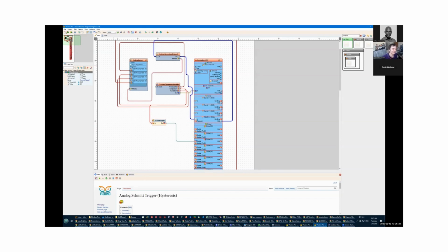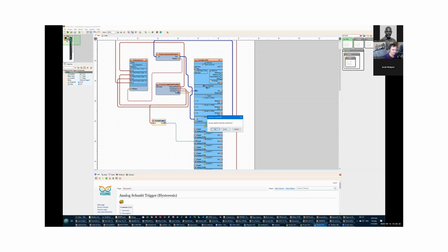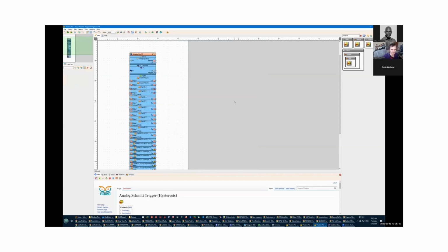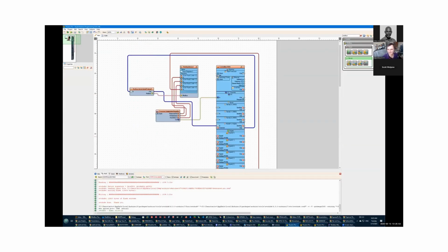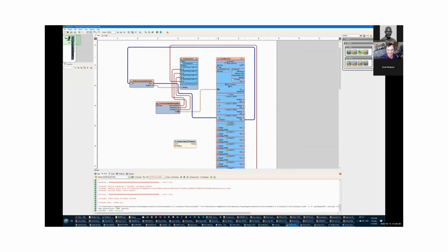But that being said, okay, let's forget about this project. I want to show you an even more interesting project. So now we have our Controllino Maxi, which works over 485. But Modbus can communicate also over TCP/IP. And yeah, I can implement TCP/IP over this Controllino. Just to show you how it can be done, I will do that here. You know what? That was not planned, but I will do it. So let's first of all change our Controllino Maxi to work over TCP/IP as well.